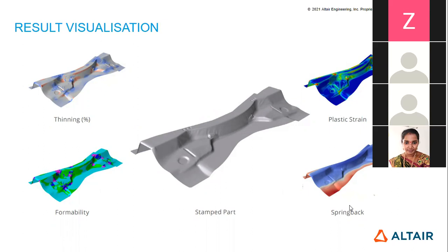So in the design process, you just design your model, your concept. Suppose you have designed a sheet metal component, but you need to check its manufacturability, because the model you design is a very ideal design. It doesn't have spring back, it doesn't have any manufacturing defect, it doesn't have any material modification. But once the metal goes to production, it gets the wrinkle, it gets the fractures, it gets the scratches during the forming simulation. So you should consider these things before designing.